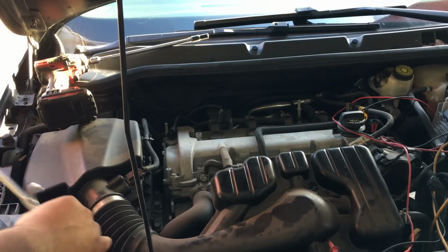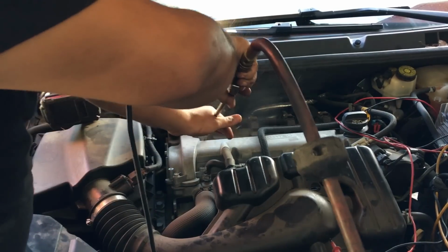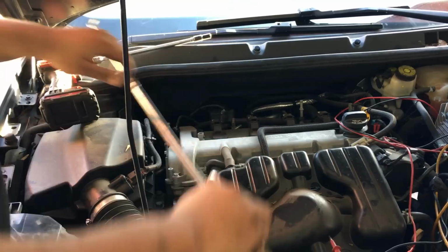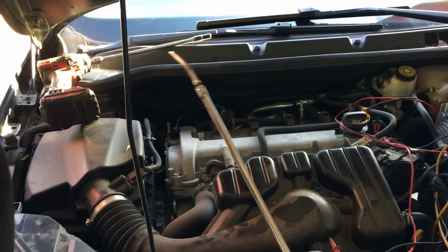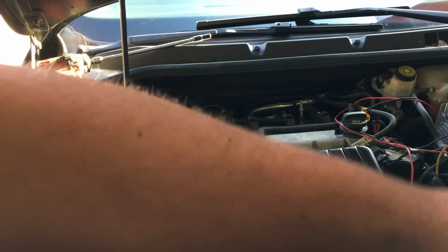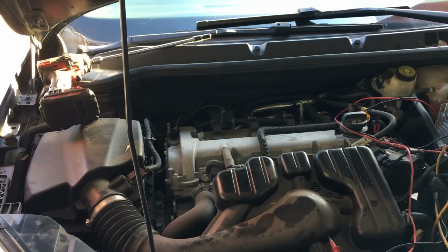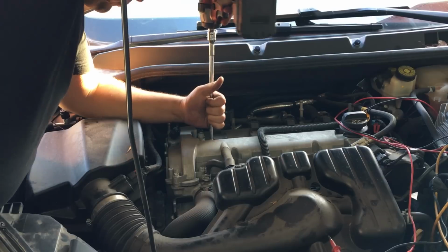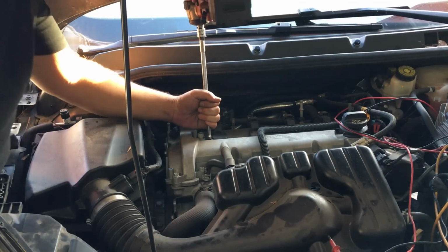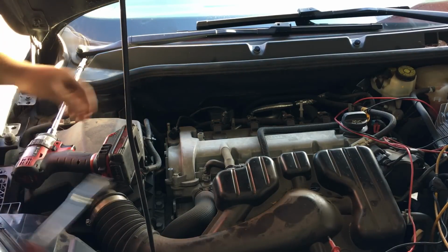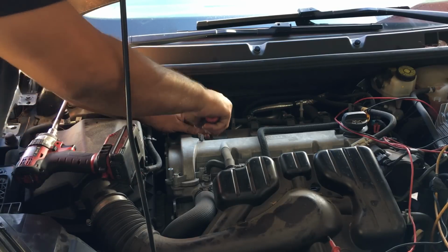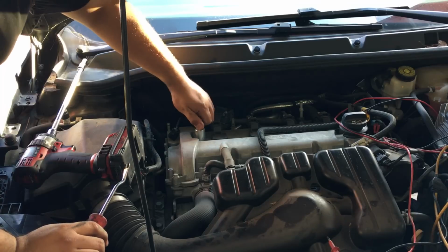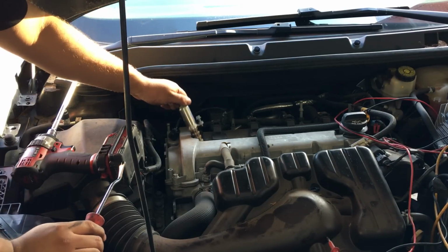All right guys, so I'm gonna quickly replace this thing, kind of blow it out with air. Make sure you remove all the dirt and debris down in the valve cover because you don't want it getting inside. Now let's go ahead and remove the 10mm bolt, and then we'll pry it out. Now these things can be pretty stuck in there. Well, this one came out pretty easy. And of course you're gonna get some oil.